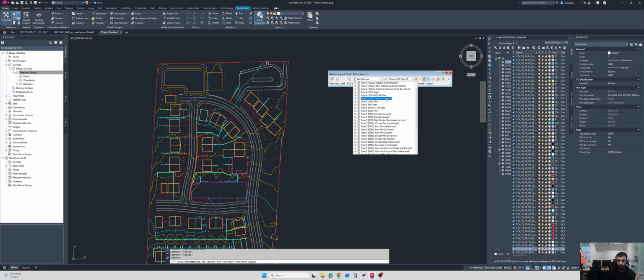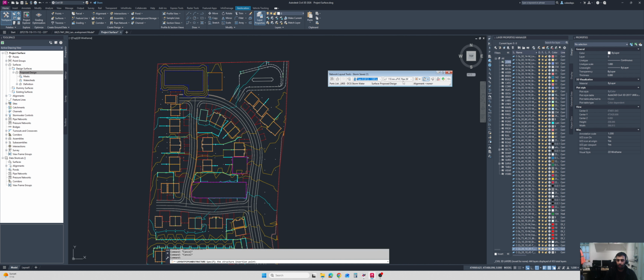For example, you have the concrete surround rigid, simple circular, or whatever manhole you want. For example, if I go for the Type B manholes for the flexible pipes, I will go for this diameter, and then for the pipes, HDPE pipes, I will go for 150 pipes.